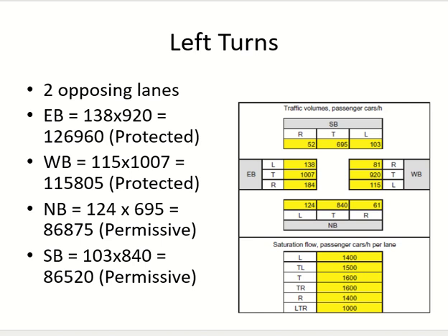For north-south, I don't have to. I just consider straight. That's it. Clear? No phase required for left turning. This is what it means. When it is permissive, no phase is required for left turning. So left turning is with the straight. Clear or not?